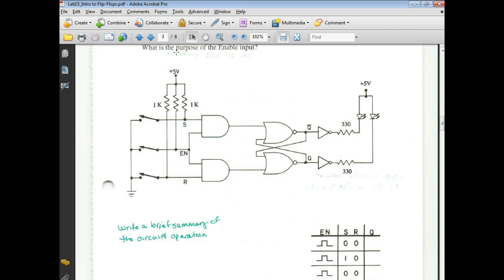I have it connected to pin 1 and pin 4. And my output of the A gate, which uses 1 through 3, so pin 3 would be connected to this guy, and then this would be 4, 5, 6. So pin 6 is connected to that guy. So guys, tell me how this thing's going to work.